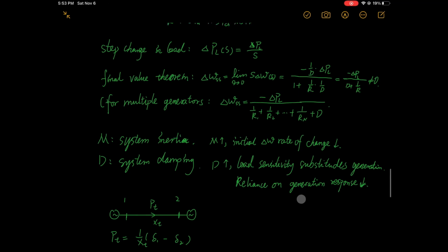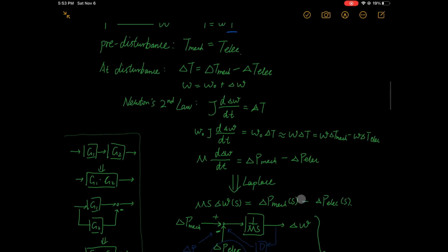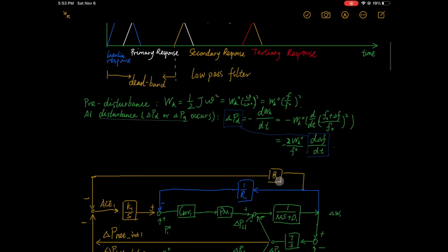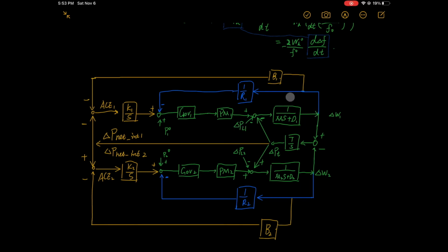Up to now, after these control efforts, the power generation and load mismatch is eliminated, but we still have two problems. One problem is there is a steady-state error on frequency, and the other problem is that there's also a change in the tie-line power flow between two interconnected regions compared with the pre-disturbance value.